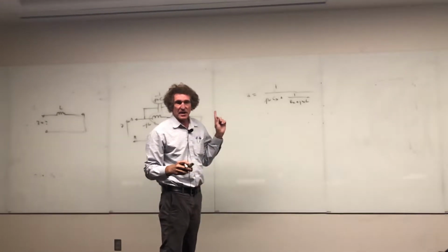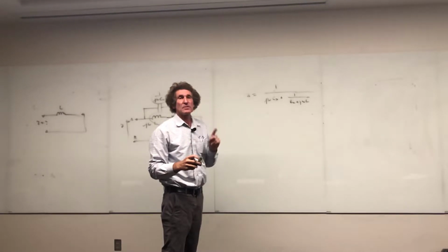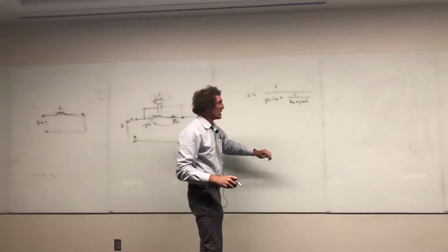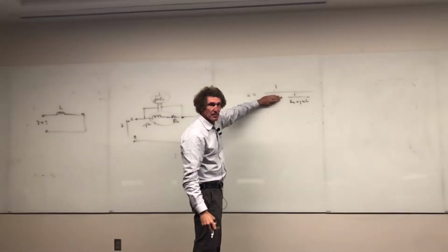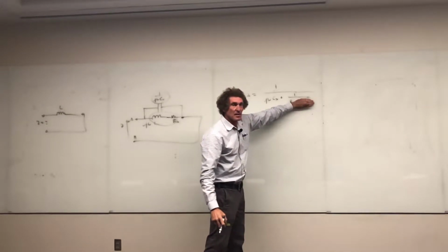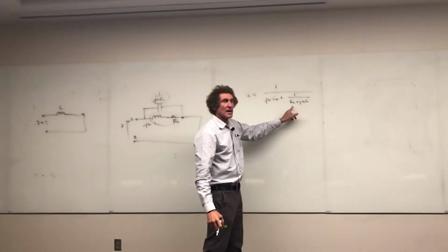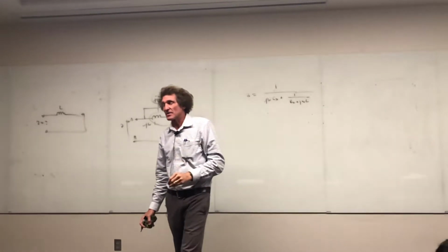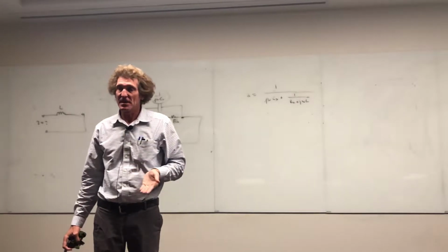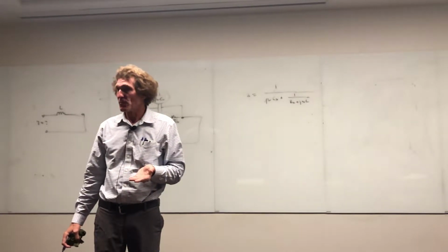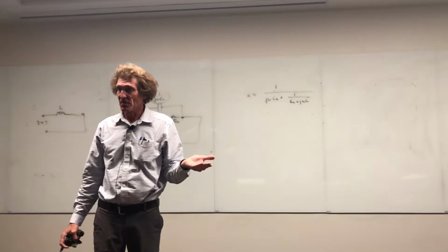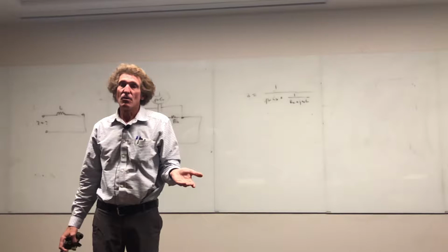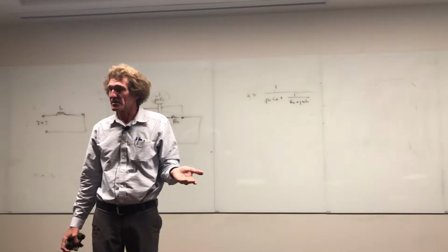Now, at very low frequencies, just observe this with me. Let omega go to 0. All right, omega goes to 0, that goes away. Do you agree with me? The only thing left is 1 over 1 over Rx, or it's Rx. Do you follow me? So the impedance of an inductor at absolutely no frequency, DC, if you had an ohmmeter and measured it, would be the DC resistance of the wire. That's it. And it's usually very, very small, like milliohms or less for most inductors.